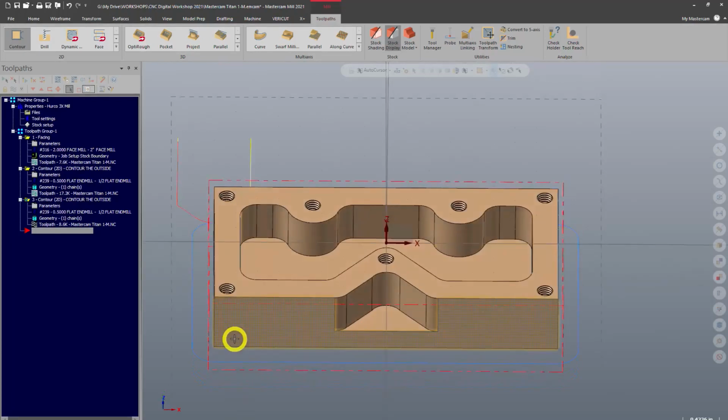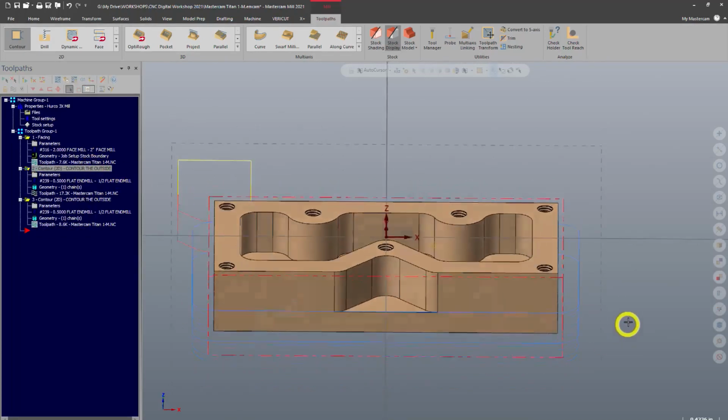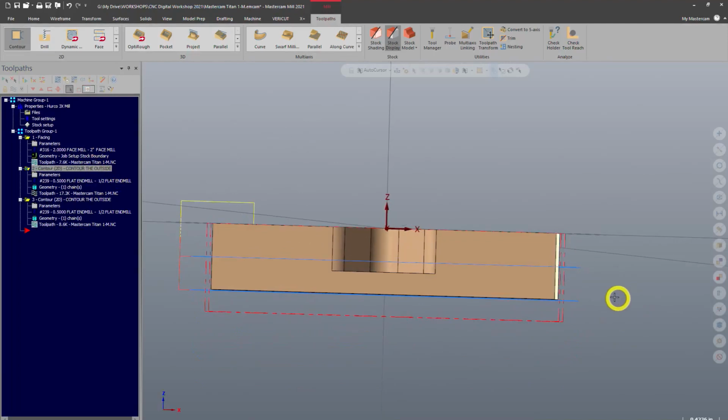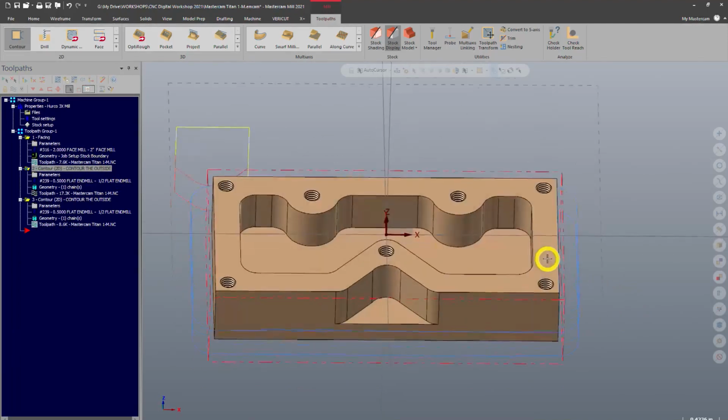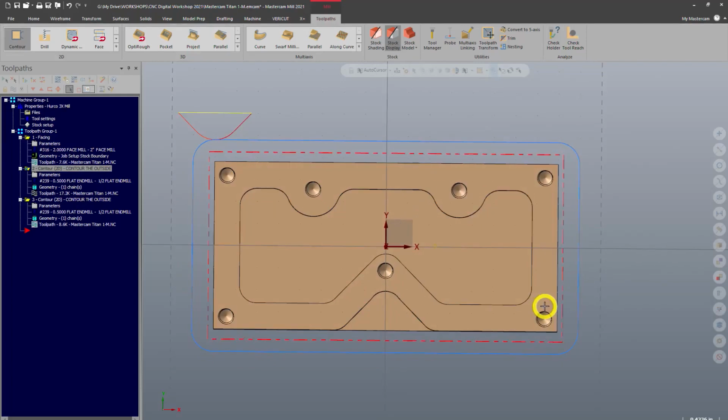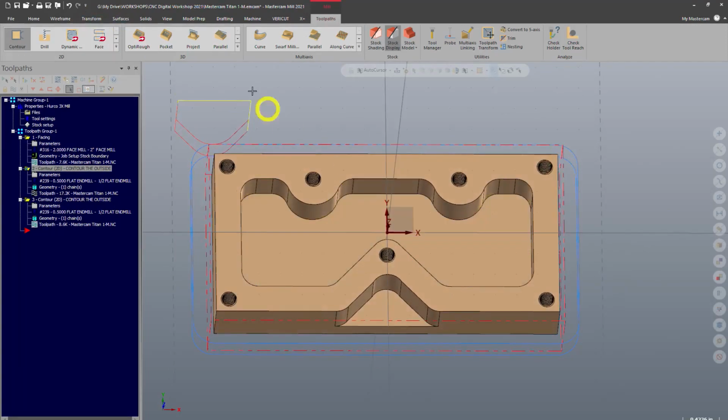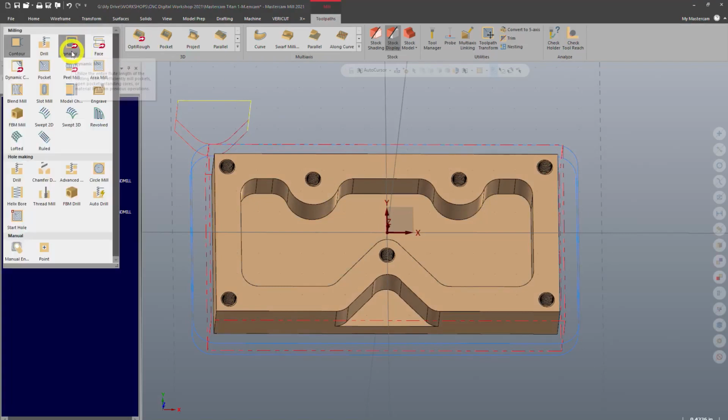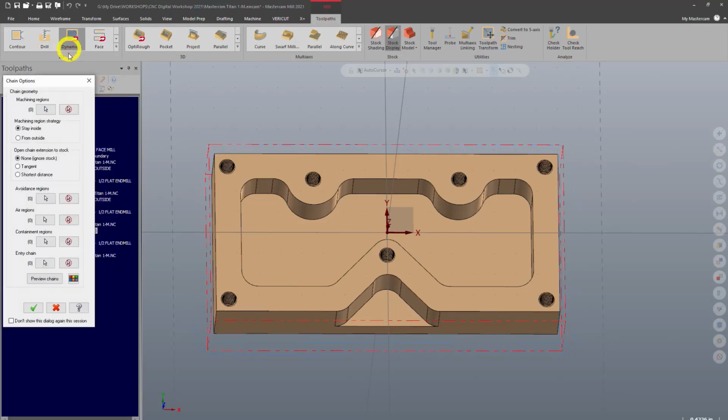So that toolpath type relies on variable width cuts. Instead of doing depth cuts, it's actually taking advantage of the width cuts, such as those multi-passes which I talked about. So in order to create a dynamic toolpath for this pocket here, we'll do dynamic mill. If it's not showing up, you can click drop down. Do not want to do dynamic contour, that's a finishing operation. So we'll do dynamic mill, utilize the entire length of the cutting tool to efficiently mill pockets, etc. So we'll go ahead and click that.